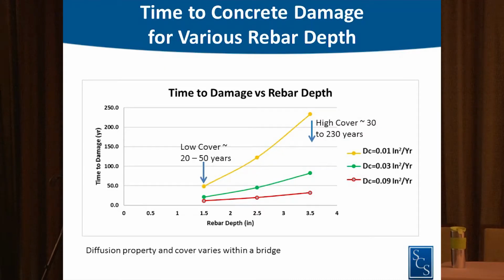For example, if your cover is 1.5 inches, there is no difference between your really poor concrete and the concrete that we use. So the cover really is your first line of defense. And second is the concrete quality. And then you go on to your corrosion resistant reinforcement, things like that, right? And we got some new ones that one of the folks, AZZ, is doing. It's a new form of zinc, I guess, right? Zinc-coated rebars.